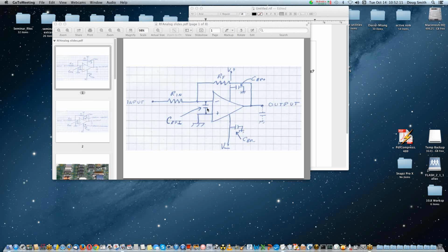If you're talking about cutting the planes, that's okay, and sometimes we do that to isolate analog circuits from noise currents flowing through them. It just means you can't bring any path, digital or analog, across that break. You have to find the common point between the two grounds and go across there so it stays over the common ground. I think a lot of people know that.